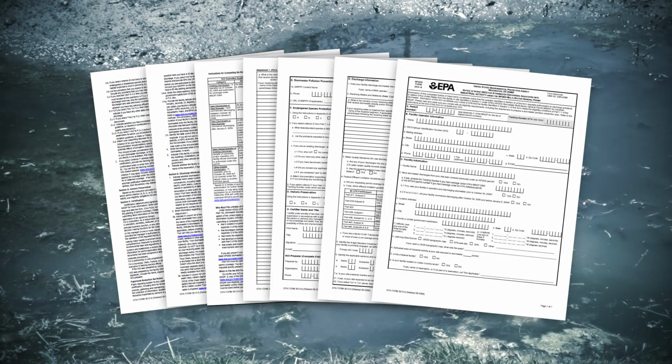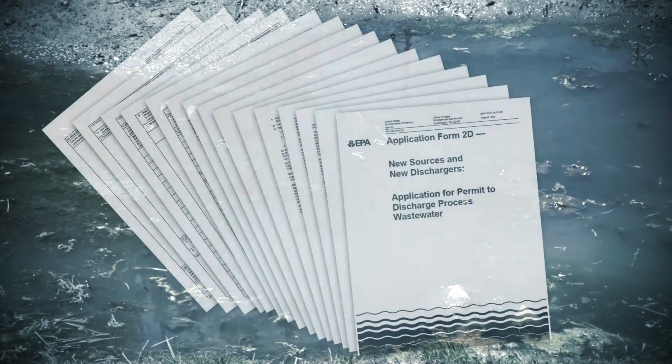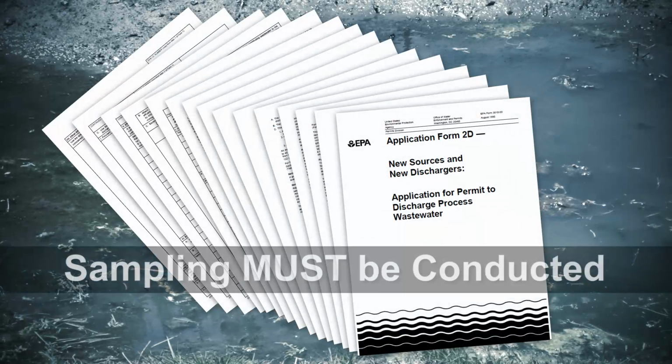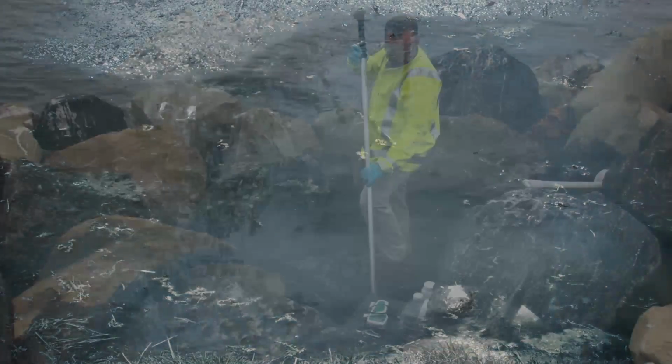Whether seeking a permit through a group application or an individual application, permit recipients will be subject to compliance monitoring during the term of their NPDES permit, including those covered by a general permit. Regardless of the permit type, reporting quantitative stormwater sample data to the EPA is mandatory. Therefore, you must conduct stormwater sampling.